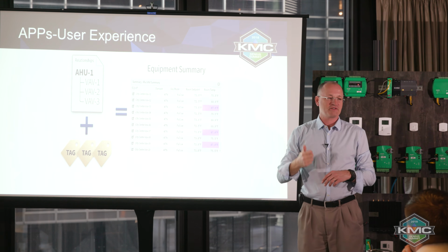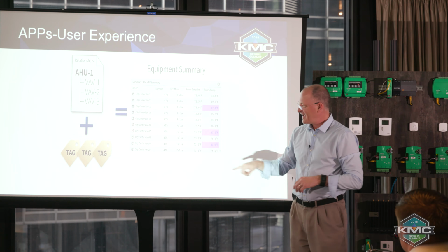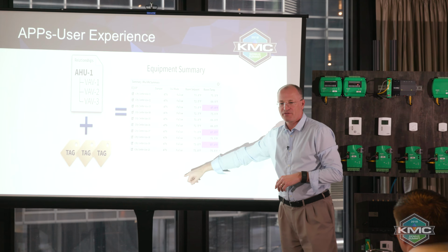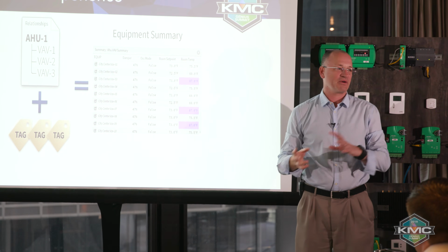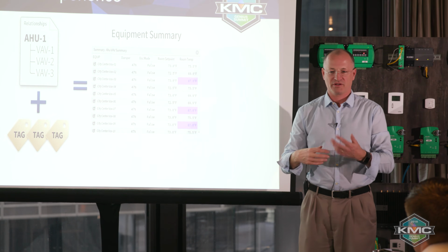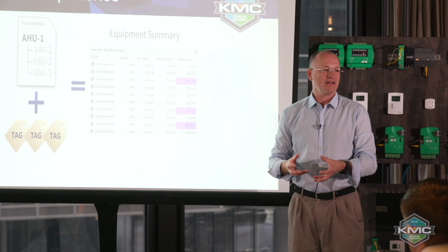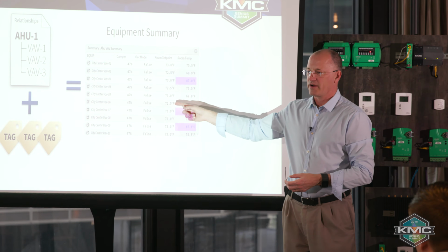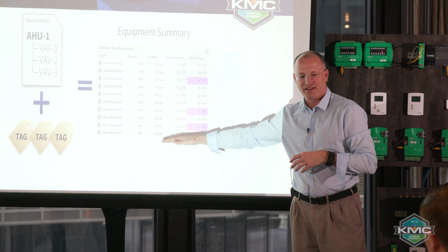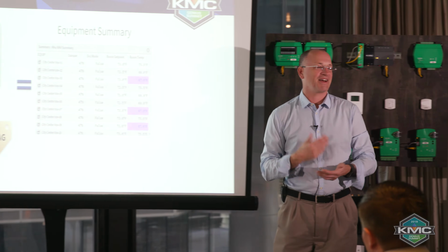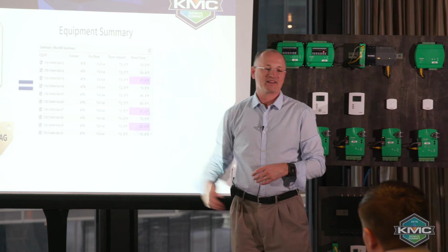So what's one of the fringe benefits of being a query? Well, if you have a technician working out in the field and he just brings on VAV 11 through 15, quite literally the next time I refresh this browser, without ever going into the graphics editor and the traditional adding things to the database, just by those things coming online and this being based on a query that's looking for a reference tag back to error handler 1, you'll see VAV 11 through 15. It's all dynamic. If I were to delete one, it would not be there the next time.